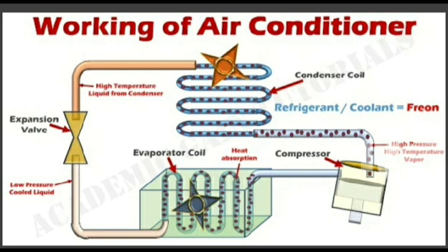This is because of the second law of thermodynamics, which states that heat flows naturally from hot to cold. As this cold liquid refrigerant absorbs heat from the indoor air, it starts to evaporate to form a vapor. Thus, the refrigerant in this evaporator unit absorbs heat from our home and converts into vapor, and as a result our home environment loses heat and cools down. This fan circulates the cold air from this coil surface for the cooling effect.